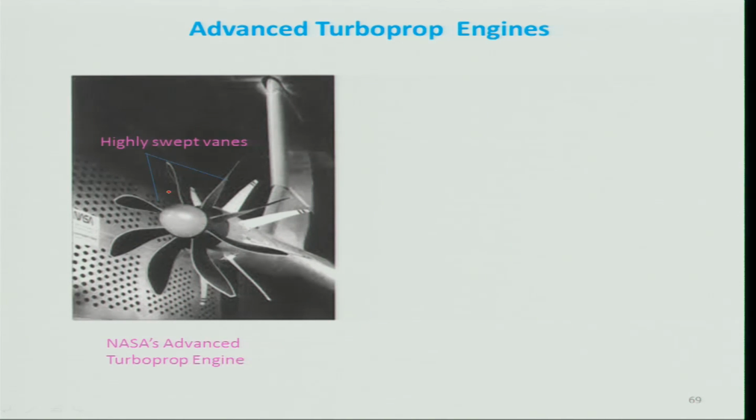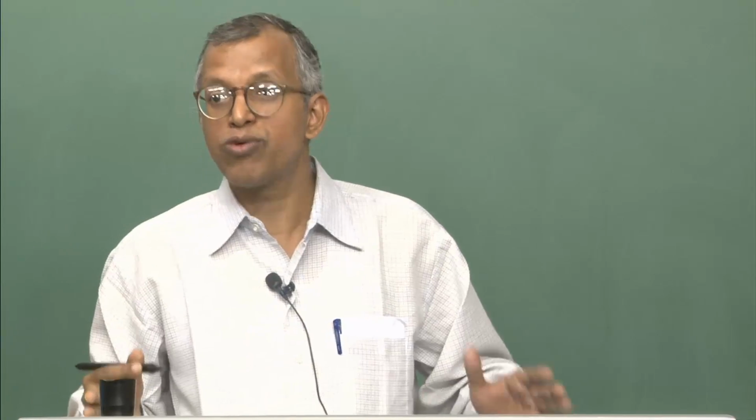because when you reduce this speed, the gearbox will be very big. Suppose your engine is operated at 50,000 RPM, you will have to bring it down to 2000 RPM, right. It will be a gear ratio of 25:1. So, the gearbox will be much bigger, because the power level of the engine will be very high. In this case, not like your automobile engine with a few kilowatts, it will be of the order of megawatts, right. So, therefore, when you reduce the RPM, you will be reducing the gearbox weight as well.